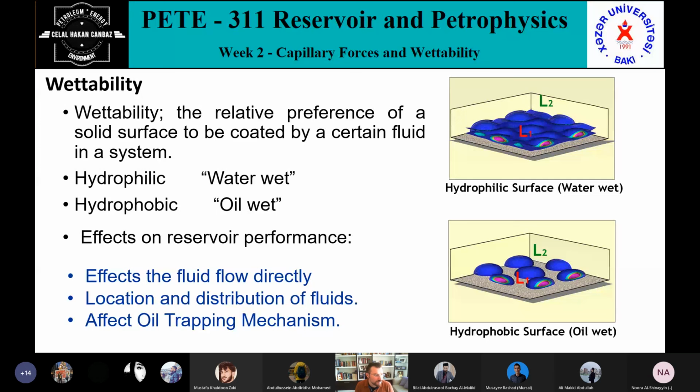Two different terms. One of them is hydrophilic, a general term which is used for all materials, in material science also. Hydrophilic means likes water. If a surface likes water, you say hydrophilic surface. In reservoir we say this is water wet. If your rock sample surface likes water, we call it water wet.